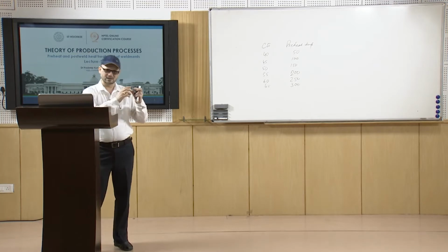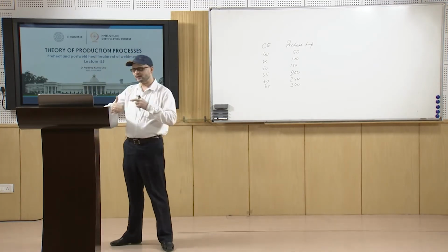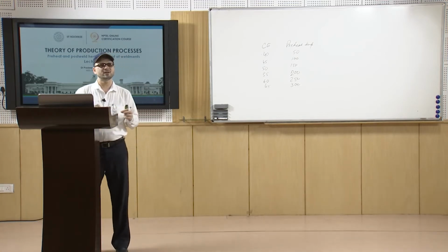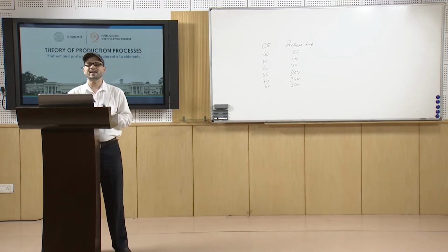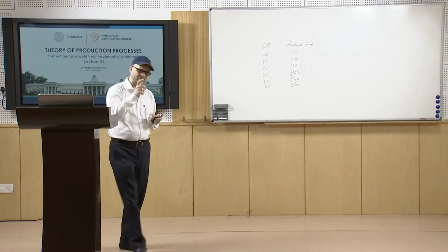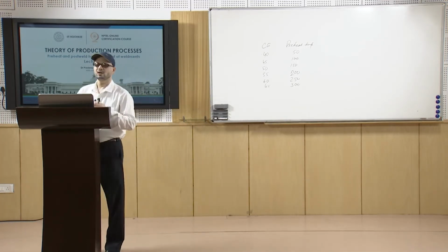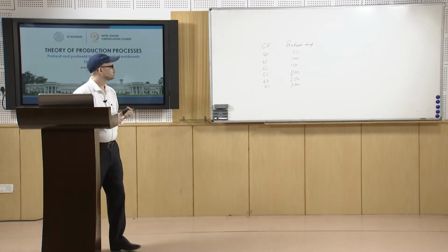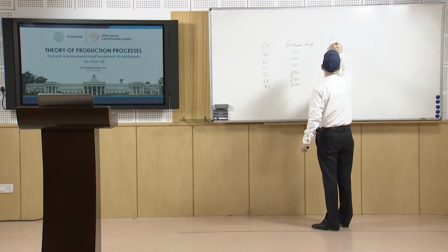So, you have these values, and this way you get the composition parameter PCM. In those cases we first find the PCM, and then from that, depending upon the hydrogen level, we also get the susceptibility index. So, basically first of all we find the PCM.